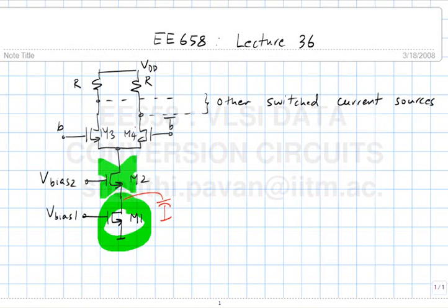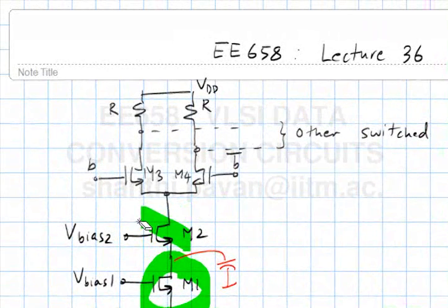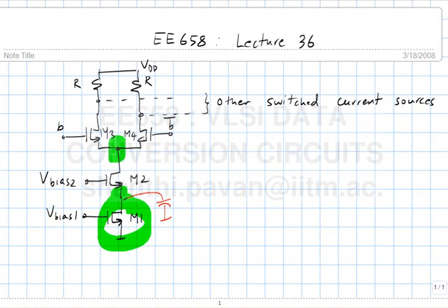Another thing is of course to minimize the parasitic capacitance. So if you did both, then you're doing as well as you can. So M2 basically isolates this node, with a large capacitance, from this node. So the equivalent parasitic capacitance at the drain of M2 is the parasitic capacitance due to the depletion capacitance between the drain and the substrate of M2, and the gate capacitances and the depletion capacitances from these sources to the bulk. So that is the sum total of all the parasitic capacitance here, which ought to be minimized.